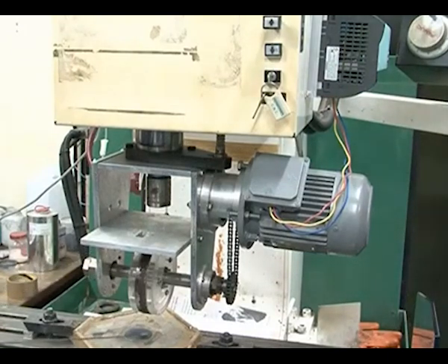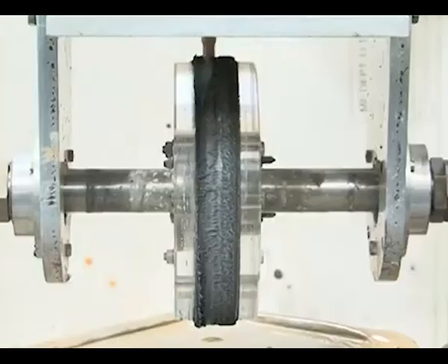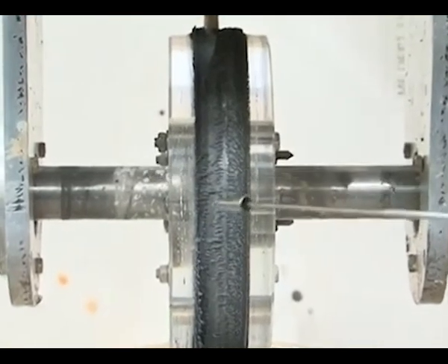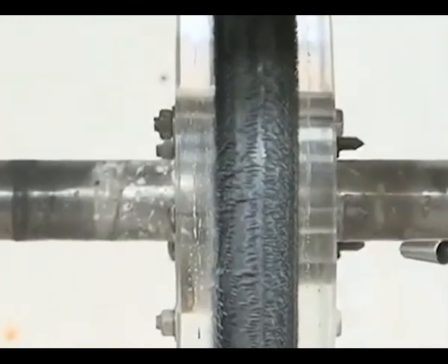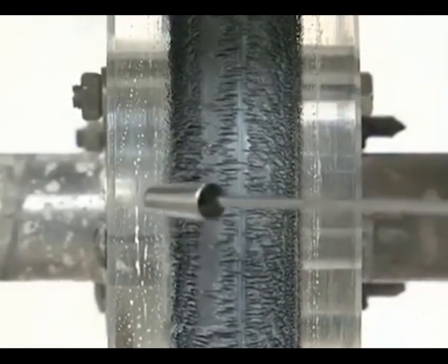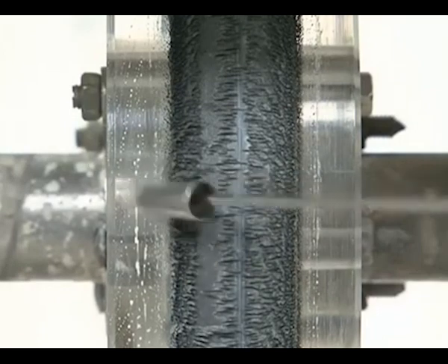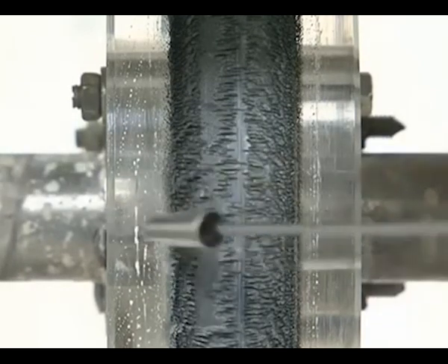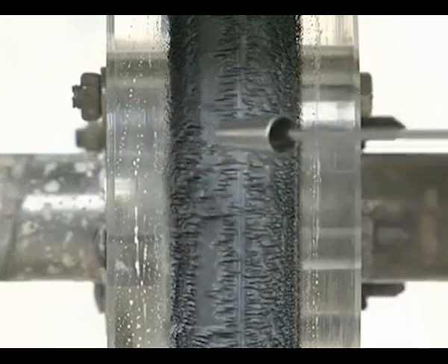This is a workpiece, and this is the workpiece fixture. In the present case, this workpiece is single crystal silicon, which is to be finished up to nanometer level by this magnetorheological finishing process. Now MR fluid is applied on the carrier wheel. Now you can see the MR particles or the magnetic particles are aligned from the north pole to south pole on the magnet. You can clearly see the chain structure of the MR fluid particles.